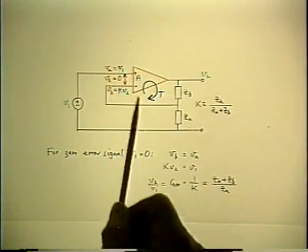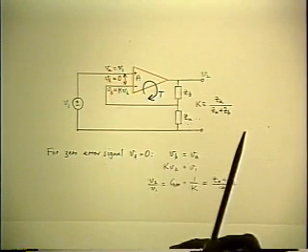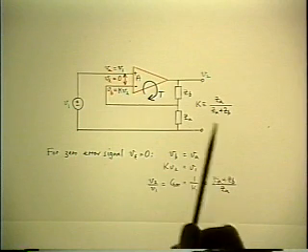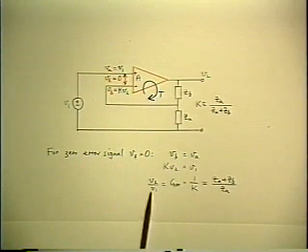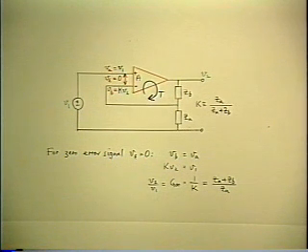Which means that the assumption that you've used to calculate this result breaks down. Which means that the actual closed loop gain is no longer equal to this ideal G infinity. That's the other part of the problem, the D part.